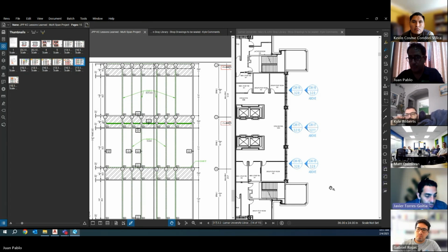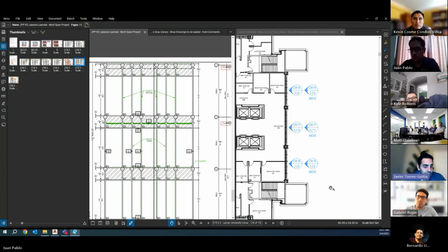So this was presented to Stuart. He was originally going to be the one stamping this project. Another important item here is that when you're making these types of judgments that are not necessarily covered by ASCE or any other prescriptive code, always run things by the engineer of record to make sure that she or he is comfortable with that approach. In this case, Stuart actually suggested using a reduced 50% of the zone 4 pressure to be applied on the fins.